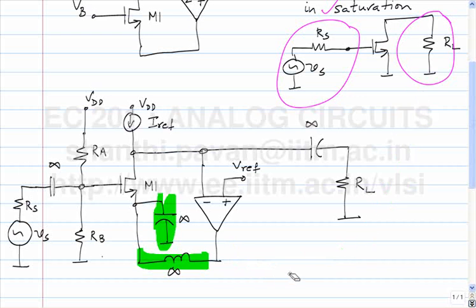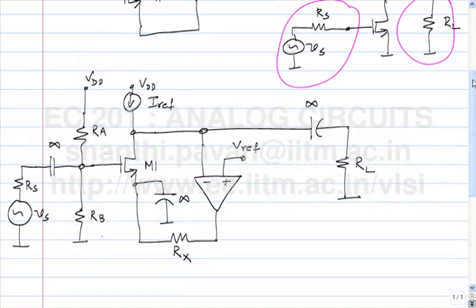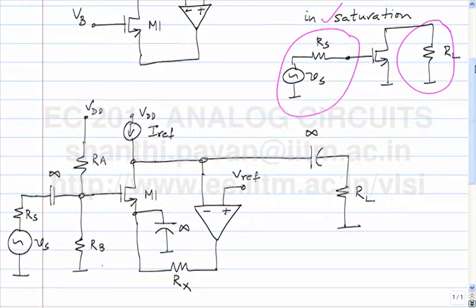And as we have discussed before, infinite inductor is a problem. So what we could do instead is use a large resistor, Rx, let me call this. Still the same common source amplifier that we have been discussing, okay, but it looks very, very different now compared to the various circuits that we have seen. This just goes to show that there are any number of circuits whose incremental equivalents can all be the same. They just look very, very different.